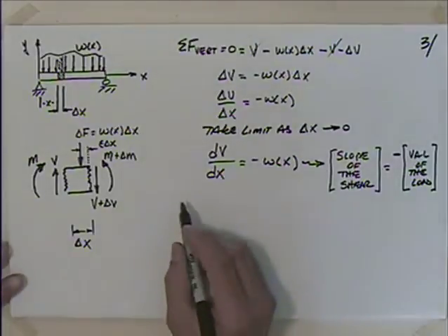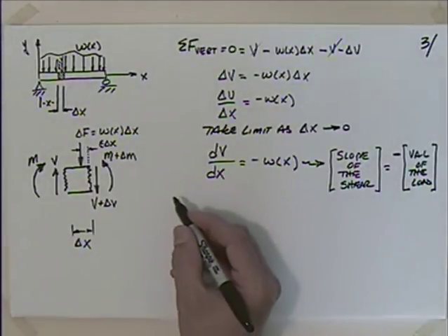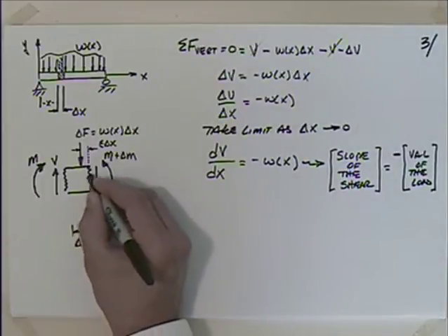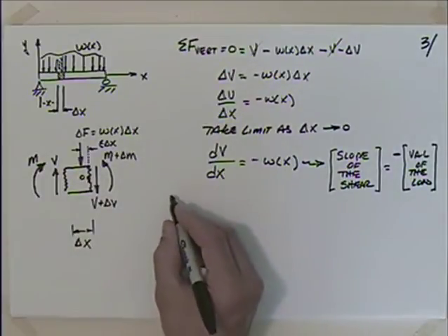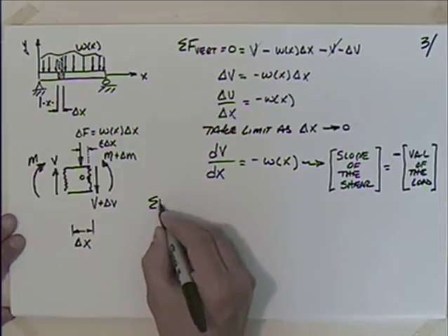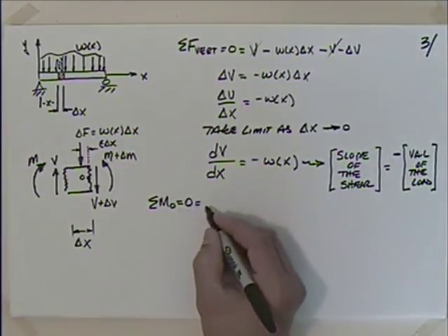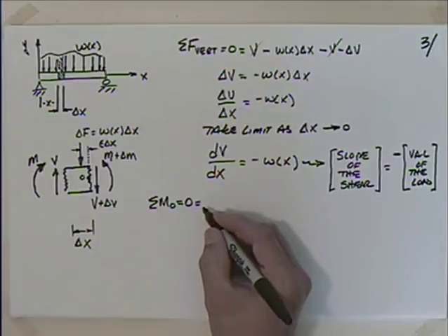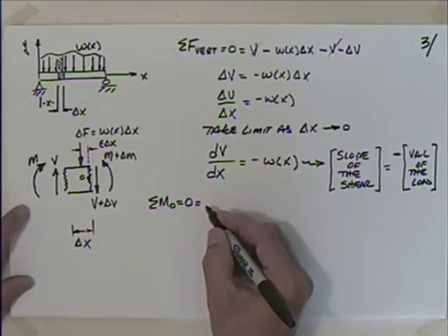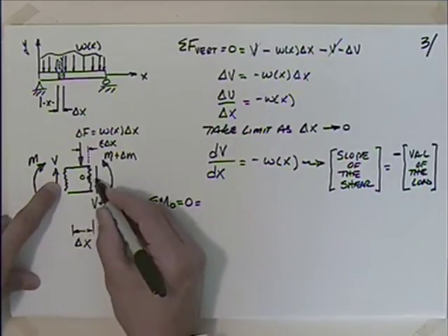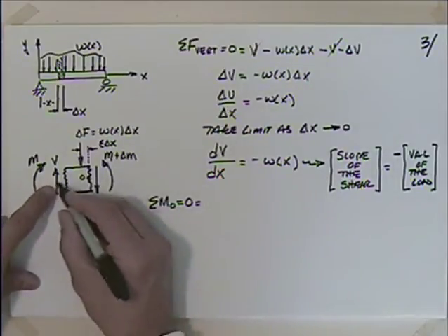Well, if I continue on and I sum the moments about the cut, and I guess we have two cuts, so I should probably be a little more specific. I'll say O there. So summing the moments about O, setting that equal to 0, what do I come up with? Well, this shear force actually intersects that point. I've just drawn that off for clarity, but this one doesn't.